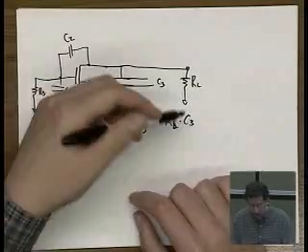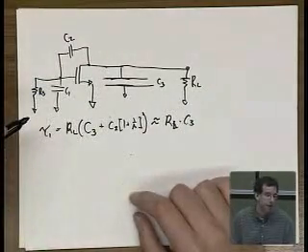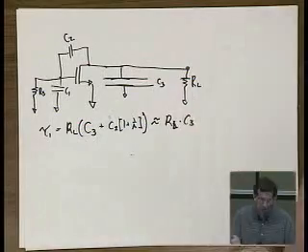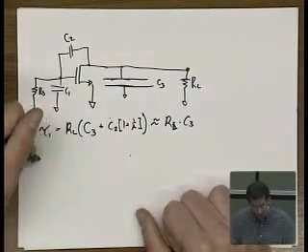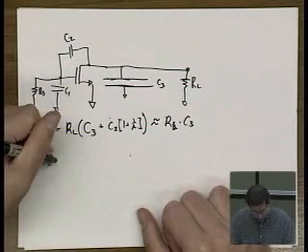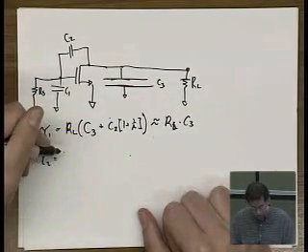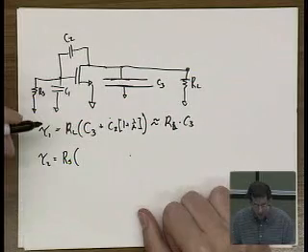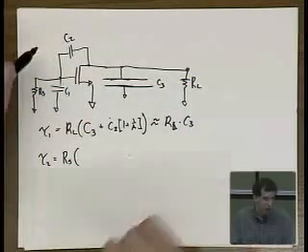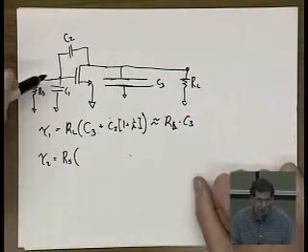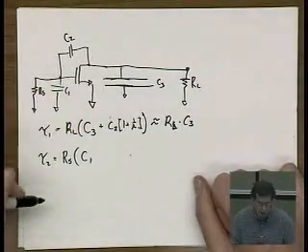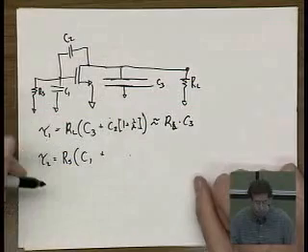Getting back to this, the dominant pole is RL times C3, roughly speaking. That's pretty easy. So the question is, what's the non-dominant pole? This could be at the input. So the resistance seen is RS. C2 can't necessarily be treated like a short yet. So what capacitance is seen at RS? You see C1, and then what happens to C2? Does it get Millerized?